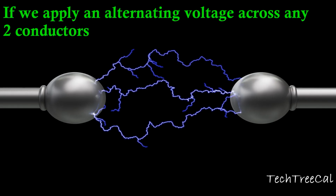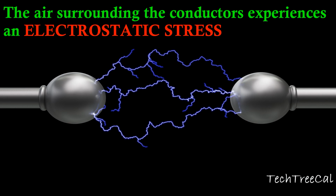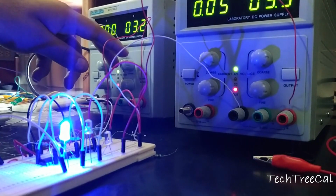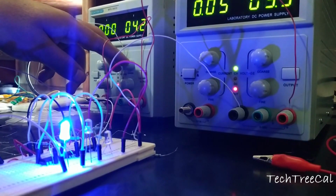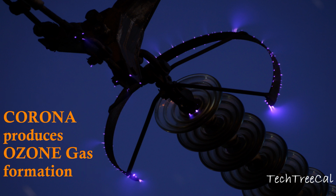If we apply an alternating potential difference across any two conductors whose spacing is large compared to their diameters, then the air surrounding the conductors experiences an electrostatic stress. At low voltage, there is no change in the condition of this atmospheric air. But whenever we slowly increase the voltage through these conductors, then a faint violet luminous glow appears on the conductors with a hissing noise. This phenomenon is called corona. Corona produces ozone gas, which can be detected by its characteristic smell.